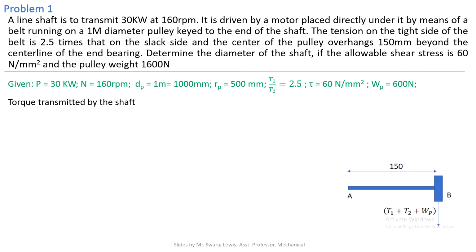First, when you're solving a design of shaft problem, you have to look whether the torque equation is given, whether they have given data for the torque. Torque is based on the power. Sometimes the data will be unknown. So in this case they have given the power and RPM. So directly you can calculate the torque by the general equation. Torque equals 9.55 into 10 raised to 6 P by N. You can find it in equation 3.1 in the data book by Balvi Reddy and Mahadevan.